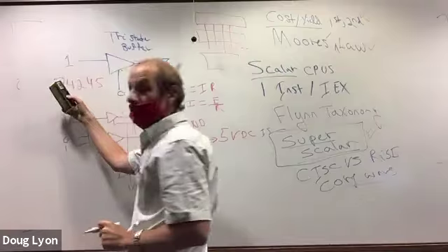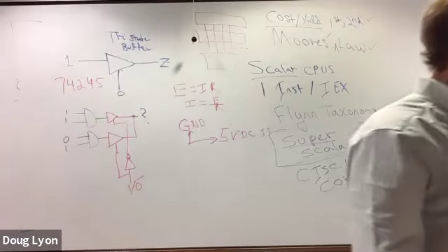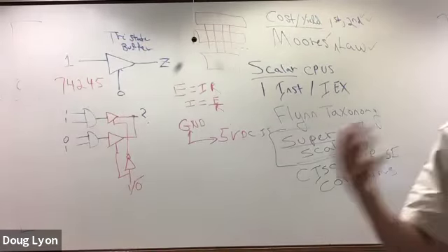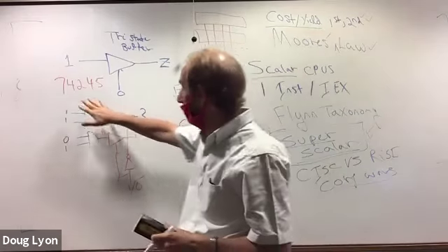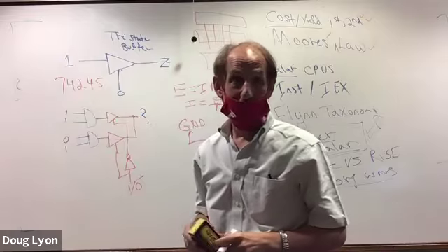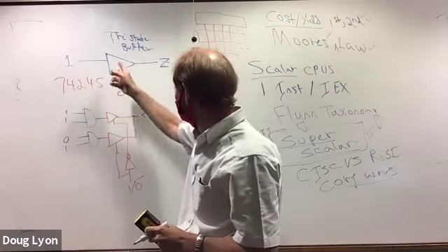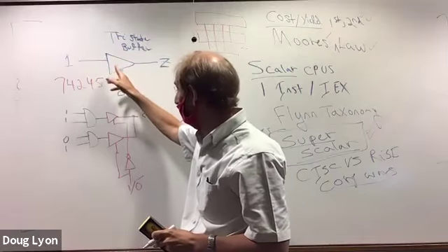And this comes in variants. You can have 74LS245. You can have 74HC245. LS is low power Schottky. HC is high speed CMOS. You can find a whole bunch of these guys, and they are 8-bit octal bus transceivers. In other words, there's 8 of these things, and they have them going in both directions, and they're all in one chip.